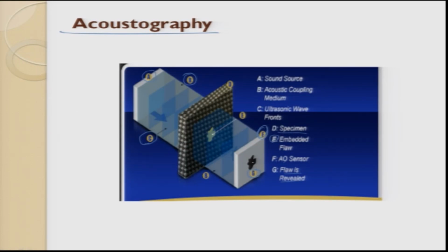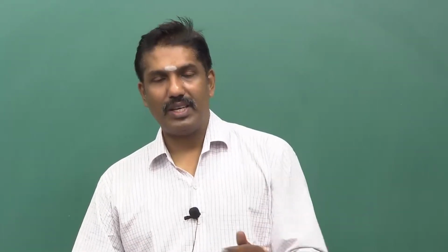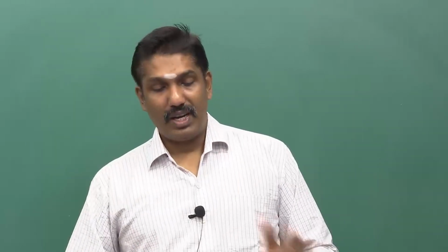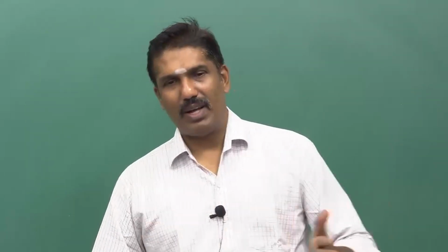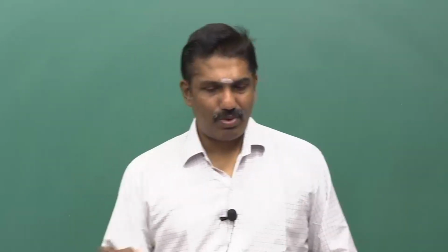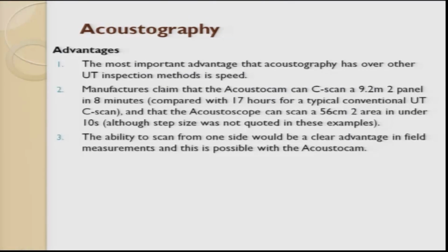Here, if you are smart, you get one area, then you can change the orientation, or change the location of the workpiece or the location of the sensor. Now I get different information in one plane. Then I change the depth and I can reconstruct the object and get a 3-dimensional way of doing it. This is the latest thing in acoustography. People talk about 3-dimensional, wherein the surface depth can also be measured by taking a combination of several things.